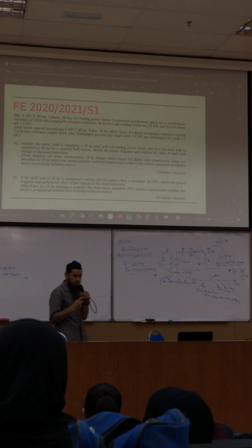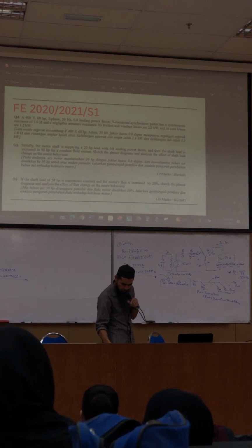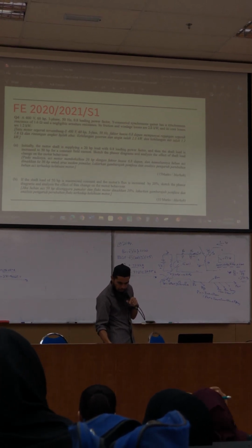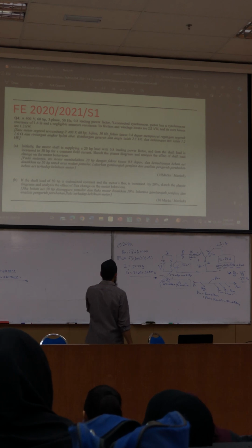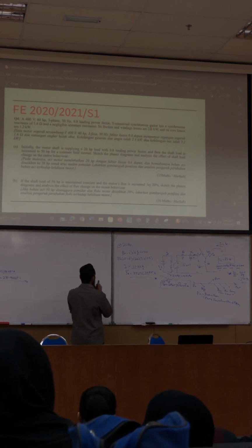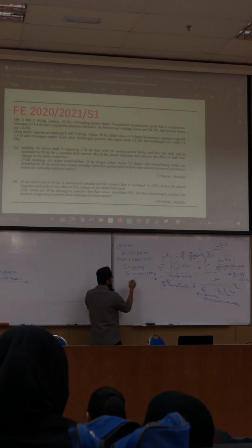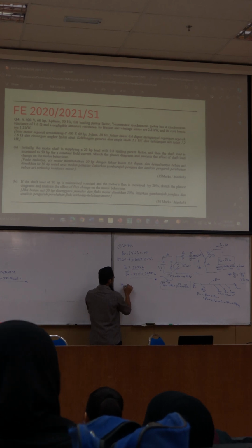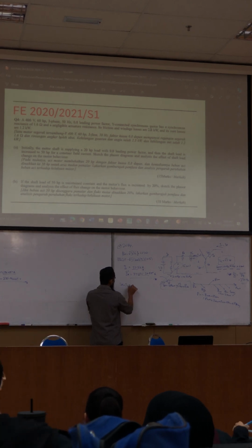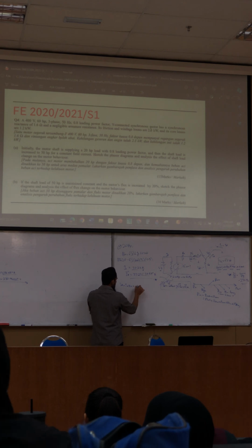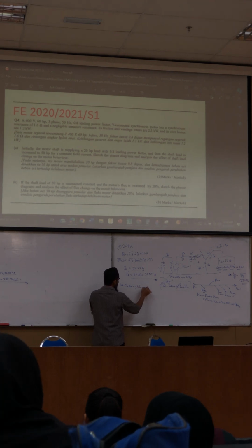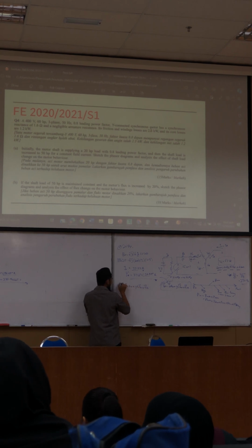Then at 20 horsepower, you find your I phase. So also at 20 horsepower, V phase equals IA RA plus jXS IA plus EA, with all the phasor marks being noted.